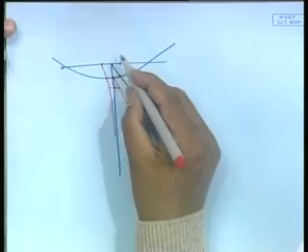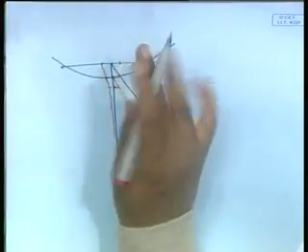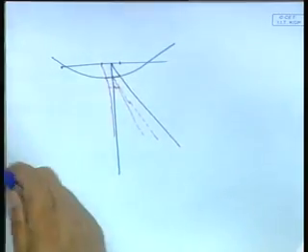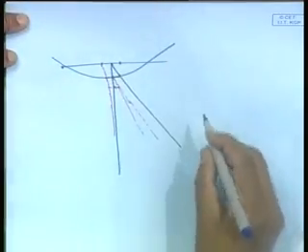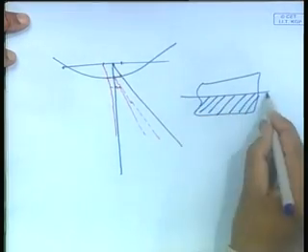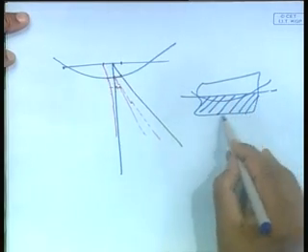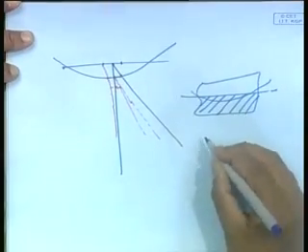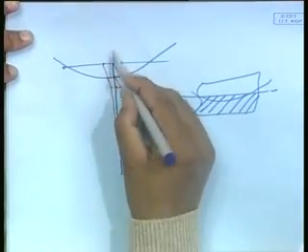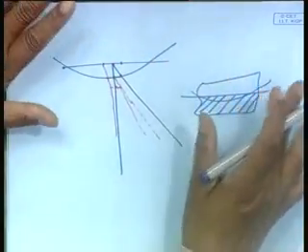The only problem that happens here is that because there is no water here, you do not have to really consider this region, because there is no water. Now I tell you why these things are important, because we will find out that in many cases of floating body structure, ultimately you will have to find the pressure over the mean water surface, even though the water is like that. Theory will tell us that we have to determine on the mean water surface, and that is why it is always good to know the pressure and use a consistent theory of z equal to 0 on the mean free surface. If z equal to 0 on the mean free surface, then you will have no problem.